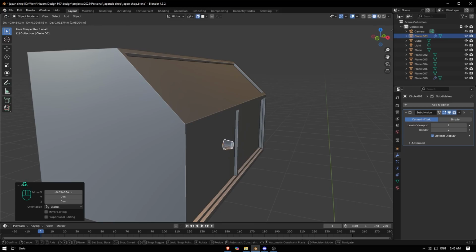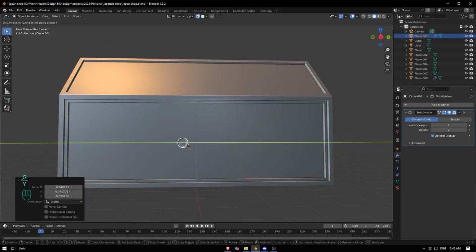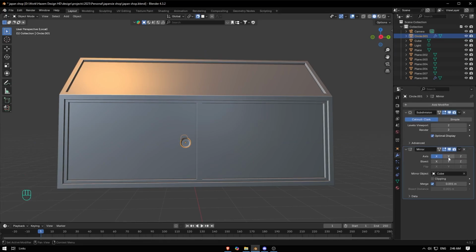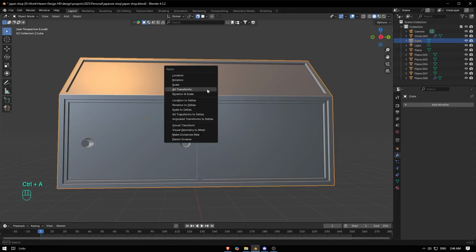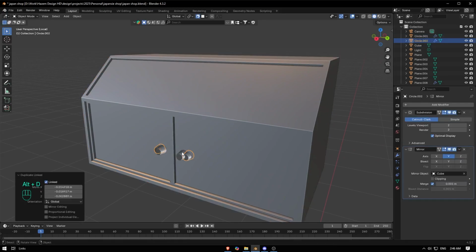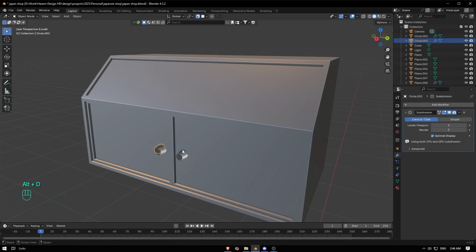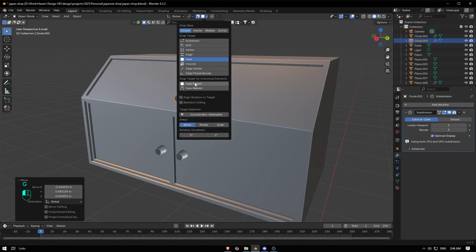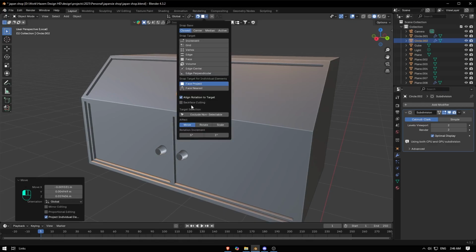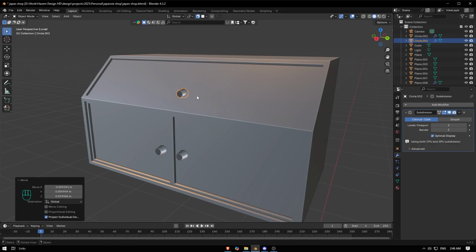Just turn on magnetic, and like this one on the face. Go here with the mirror. So mirror on this object, y-axis, yeah, I need it on the y-axis. Just going to apply origin to geometry, and for this one too. So now we're good, and just Alt D to fake copy and disable this mirror and boost it like here. Turn on magnetic. I think I need to turn on face projection and align this one. Move and rotate.